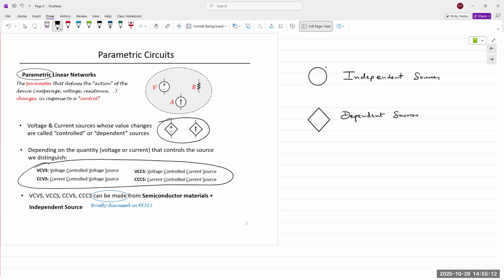But now, what if I change the 9 volts input to 18 volts? What will happen to my output then? The output that was previously 1 volt will go to 2 volts. So now, as a source, it is supplying 2 volts, but it depends on the input voltage. So a resistive voltage divider network can be considered to be a voltage controlled voltage source.